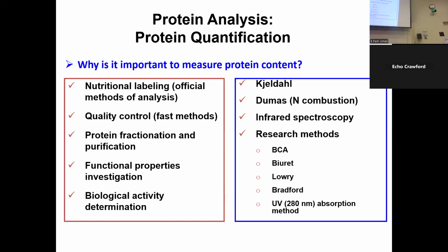So it should have a certain protein content to verify that you actually removed the bran, instead of going with fiber content, for instance. So on the line, as it's coming out of the mill, you take a sample, you put it in the IR. You got 12% protein, you're good. If you get 13% protein, not really expected.